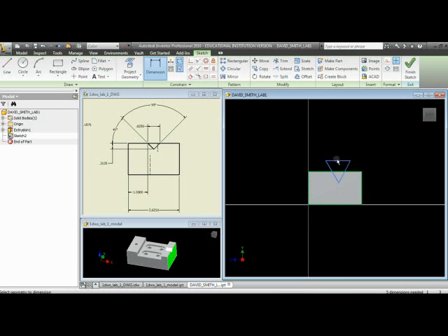Again, I right click and I can hold that left mouse button down and move it down or up to zoom. Right click and hit pan, and I can hold the left mouse button down and pan, and I can just keep zooming and panning back and forth till I get what I want here. And it's that left mouse button, and then right click and done.